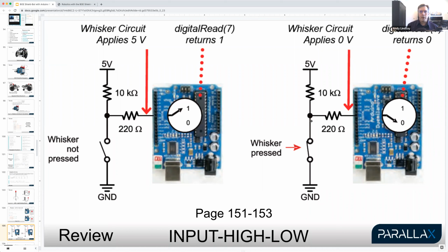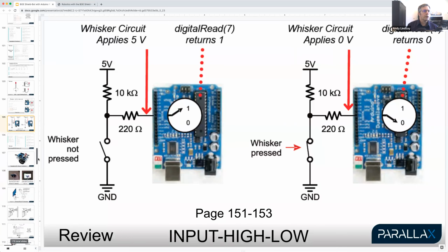The pin might see ground, but if you opened the contact and there was no resistor here to basically supply 5 volts so that it forces it to a 1 state, what happens is, if you don't have that resistor, that large resistor connected to 5 volts, this IO pin and the resistor connected to it become an antenna. And then the 1 or 0 state is pretty much at the whim of somebody walking by with a sweater that has static electricity on it, which happened to me in college, by the way.